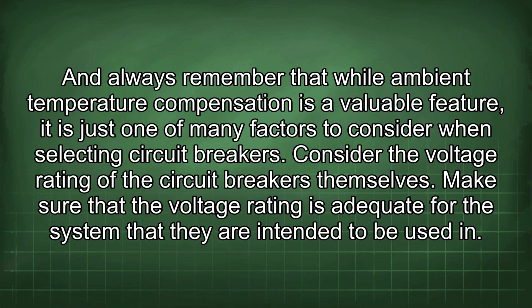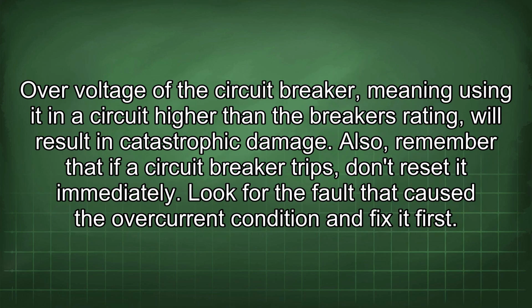Consider the voltage rating of the circuit breakers themselves. Make sure that the voltage rating is adequate for the system that they are intended to be used in. Overvoltage of the circuit breaker, meaning using it in a circuit higher than the breaker's rating, will result in catastrophic damage. Also, remember that if a circuit breaker trips, don't reset it immediately.